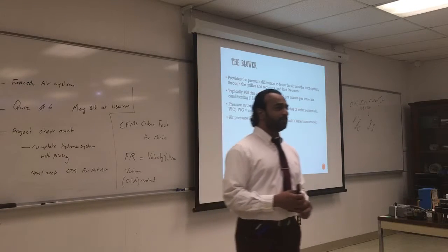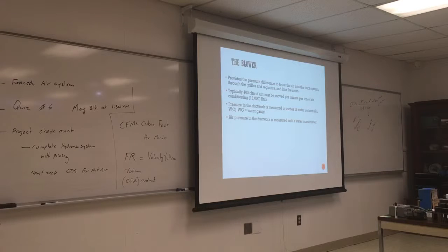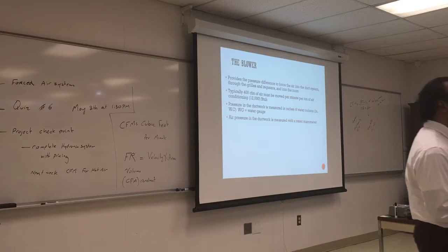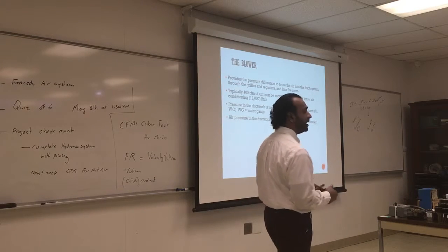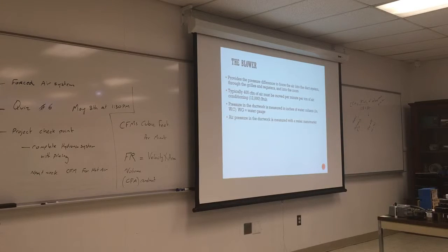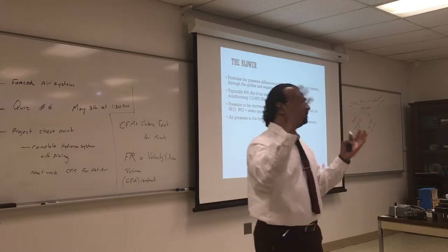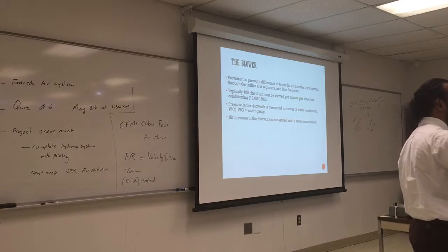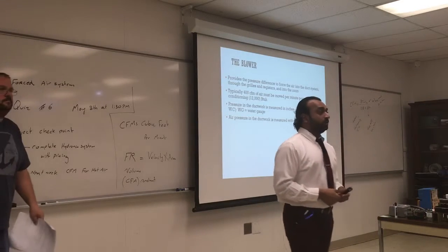I don't know if you did that with Bill, probably did last semester when we did principles of refrigeration, where you want to measure the velocity of air because you want to make sure the air is flowing the right way. So we measure the velocity of the air inside the duct using a manometer. The other way to measure it is using the hood. You cover one of the registers and calculate the CFM. There are two ways. Either you use the hood, or use the velocity with that little fan that will give you the airflow, or you can use a manometer.